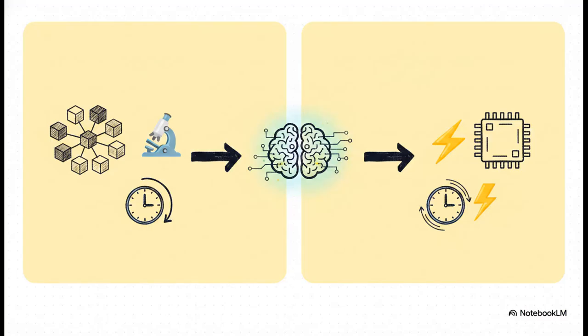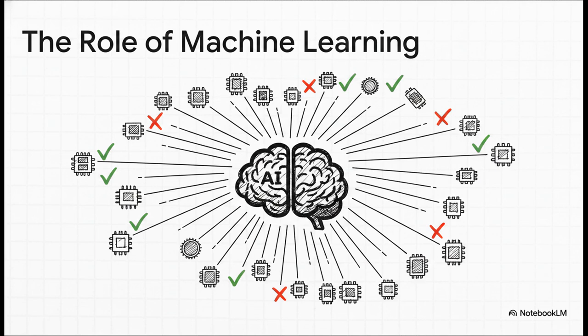So here's the game-changing idea. Instead of running a super slow, physically perfect TCAD simulation every single time you have a new layout idea, what if you could use that data to train an AI? You create what's called a surrogate model, basically an AI that learns the physics so well it can give you an instant prediction. Using machine learning techniques like Gaussian process regression, an AI model can learn that incredibly complicated relationship between the layout geometry and the physical stress it creates.